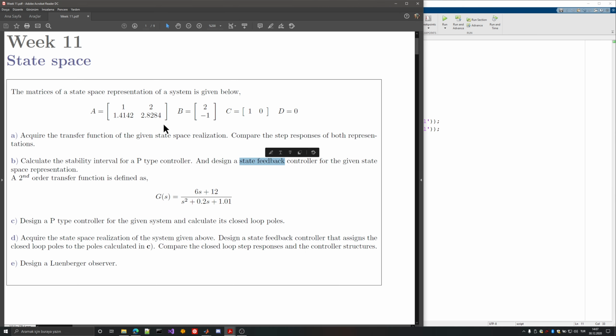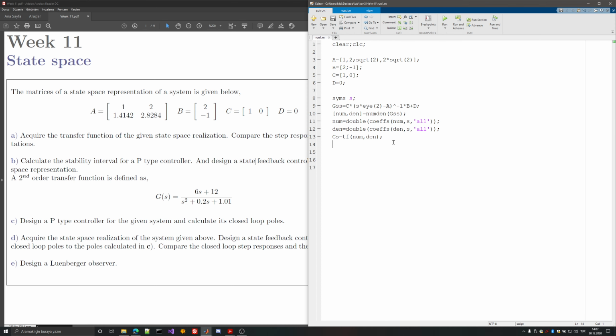I say try to because this is a deficient system. Not all systems are like this, but I have chosen this especially for the sole purpose of showing the advanced problems here instead of the usual conversion. Okay, now since I have G(s), I can just use the root locus, and even this root locus will be very simple because it's an integrator.